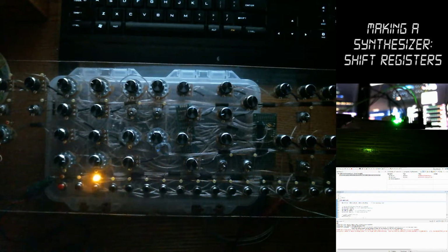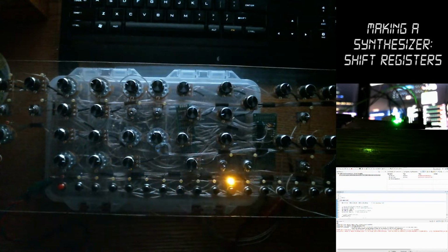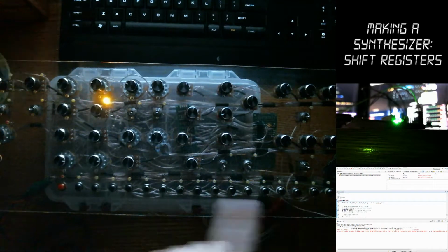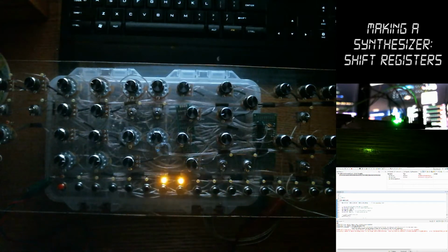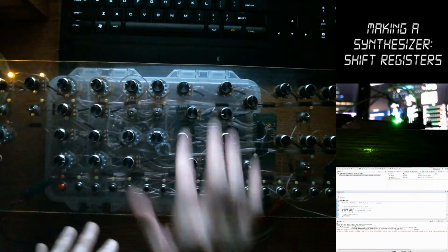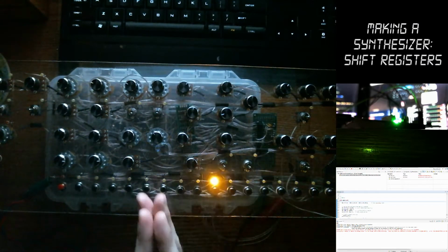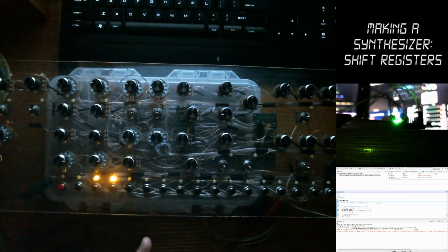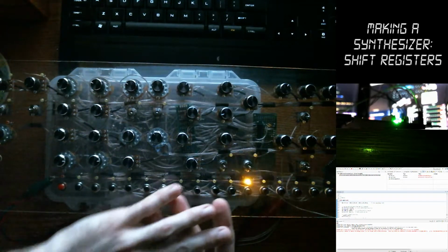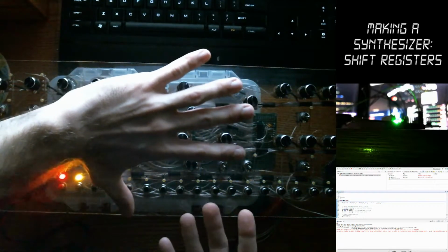Those will also all be controlled by another set of shift registers, where there will be 2 shift registers just blinking their output like this, signaling one at a time, and it'll go to a whole bunch of the digital inputs here, and the whole line of digital inputs that'll be hot at that point will go to their own inputs to the microcontroller. So you get this matrix sort of where you have inputs going into things and then outputs going into the microcontroller.